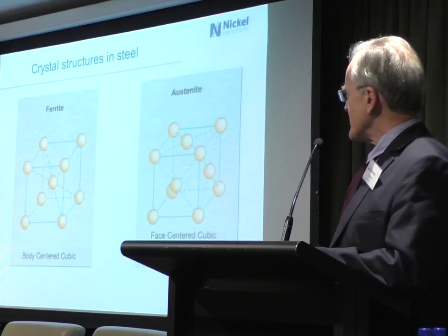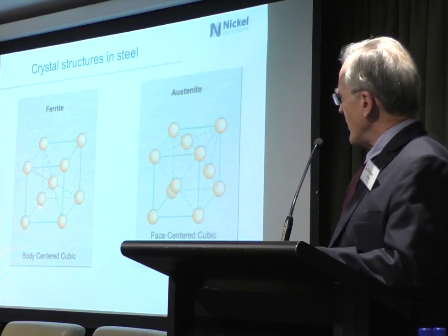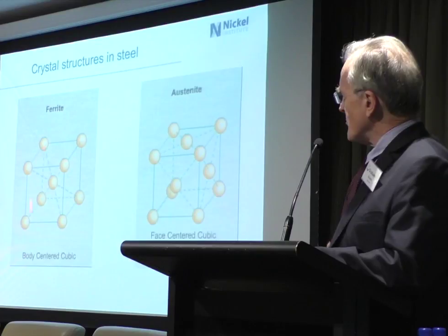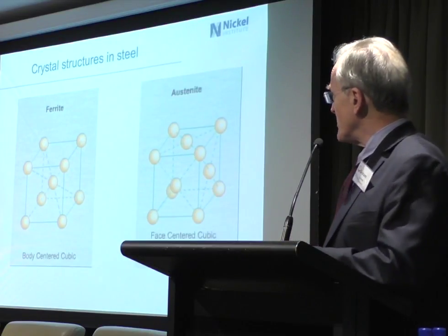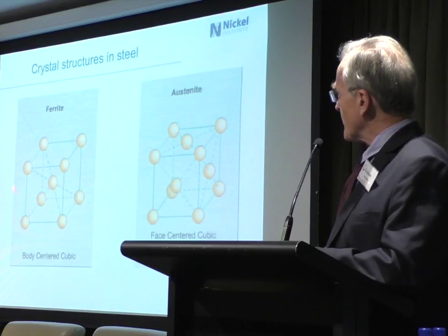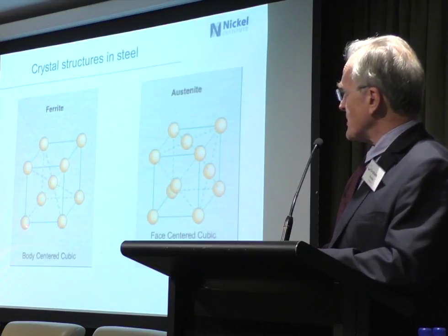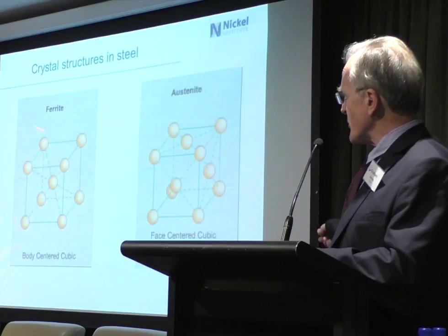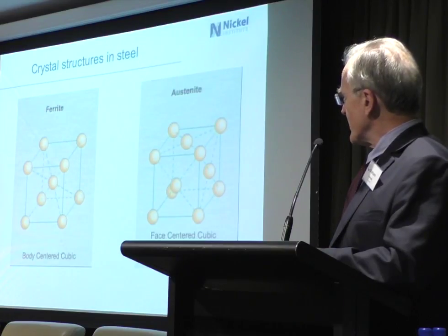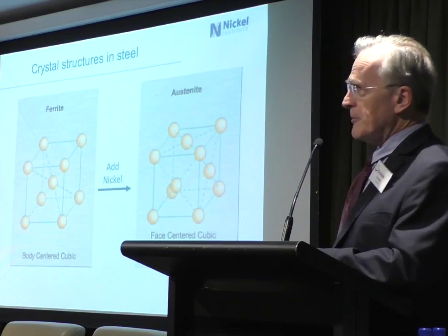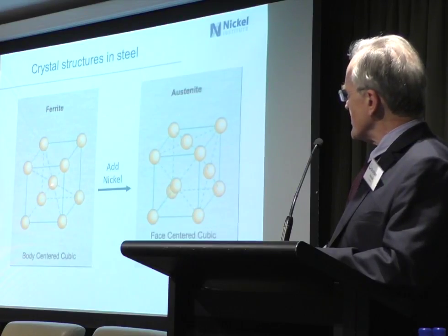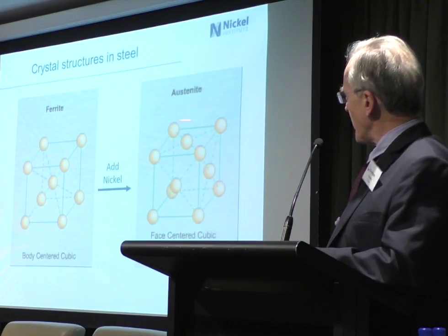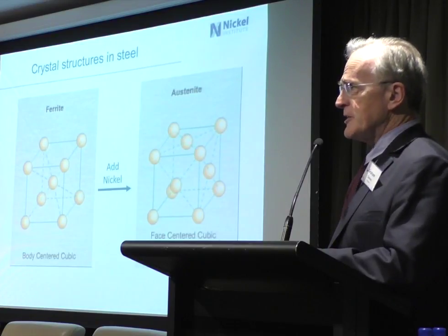All right, now this is a nice little picture of atoms cooling down, solidifying. It's very first year materials, I'd imagine. And you've got a beautiful body-centered cubic. All the iron atoms or the chromium atoms or whatever's there. If you add some nickel, and I'm sorry my animations went a bit screwy, that's a bit bigger. You can't fit it in there, so they all come out and they pop onto the surface. Your nice little face-centered cubic.